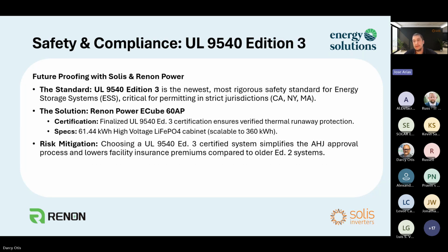And regarding working together with Renon, we have different solutions from Solis. We have 30, 40, 50, and 60 models already available, hybrid inverters at 480 volts AC, 3-phase, and also we have 208. And the solution that we are already offering in the market is together with the solution from Renon, named eCube 60 AP. It's a lithium iron phosphate cabinet, high voltage, because it's commercial. The starting size of the battery bank is 61 kilowatt hours, and you can scale up to 360 kilowatt hours.